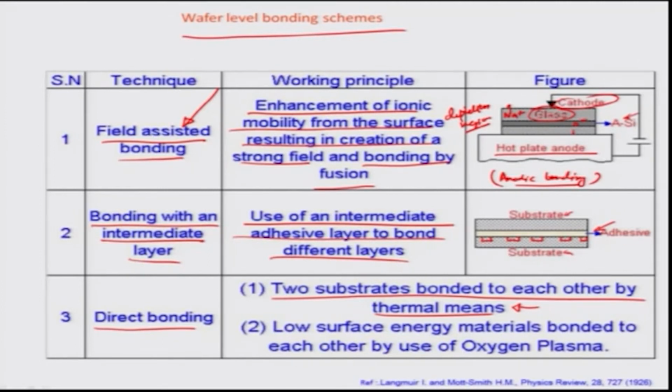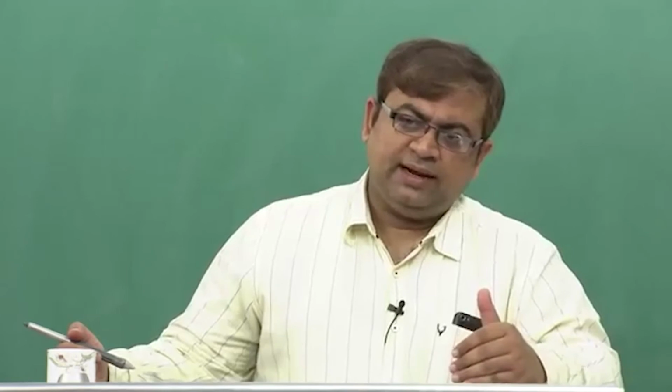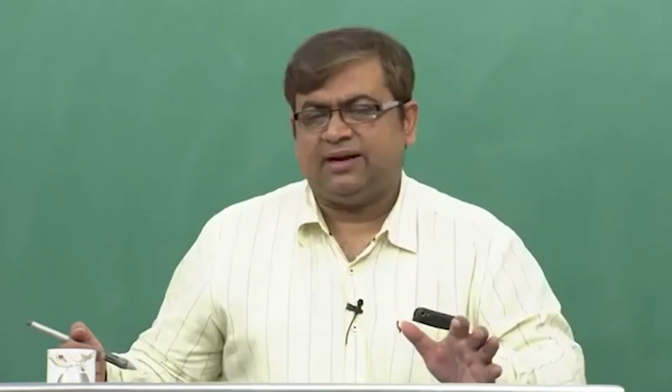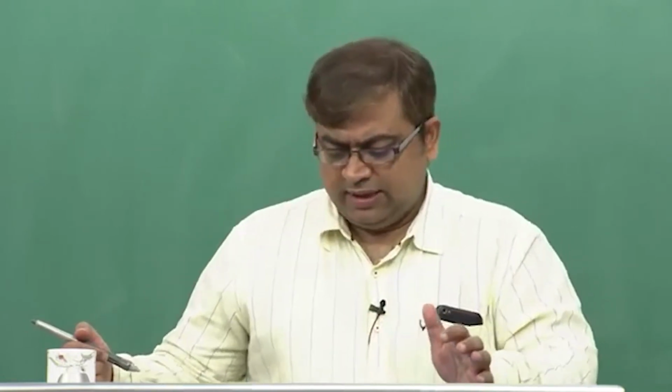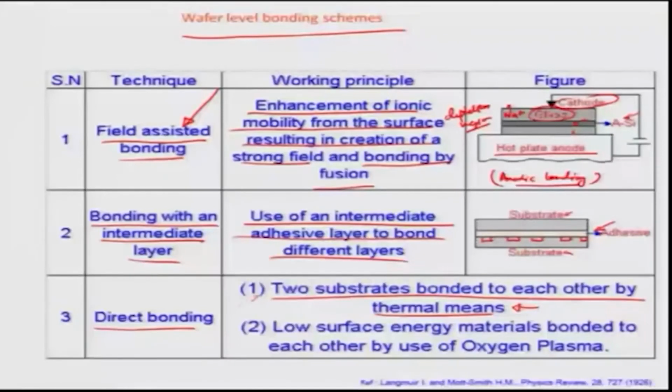But again, thermal processes are really not preferred, because thermal stresses are induced, and there can be a warping or a change in the characteristics of the wafer, and there may not be good bondability between them because of that. So typically we try to avoid creating such defects in the structure we are working on, and therefore thermal bonding is not a very preferred means when we talk about microstructuring alone.